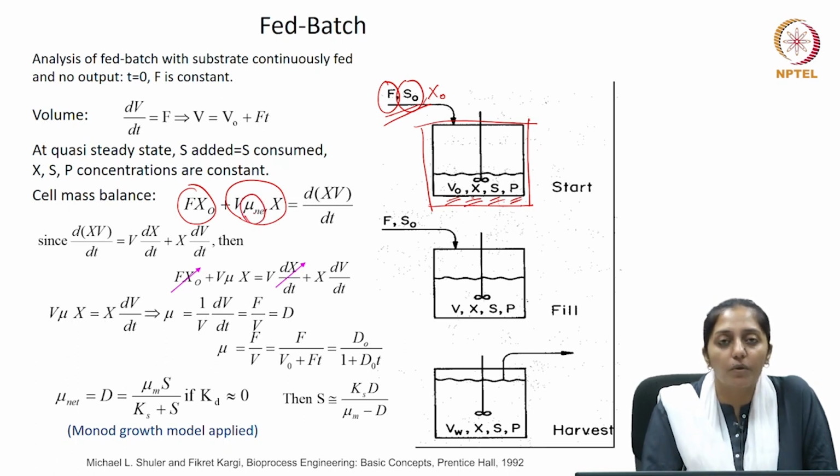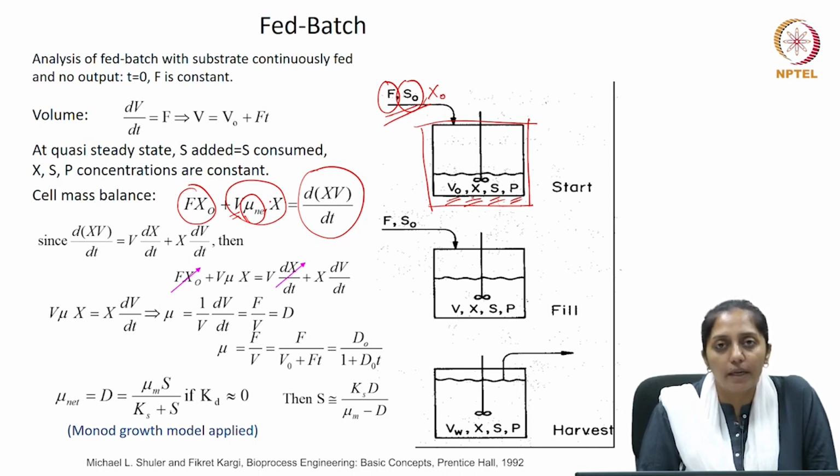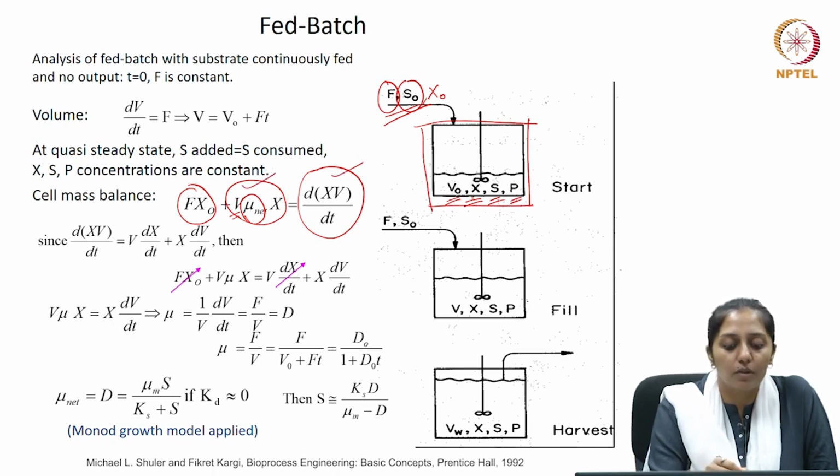It is talking about the rate at which the biomass is growing inside the reactor with a volume V at a time, and this is equal to the rate of accumulation inside the reactor. Now, the outlet term is 0, there is no consumption, so the consumption term is also 0. Therefore, we only have accumulation, growth and inlet in the continuity equation.